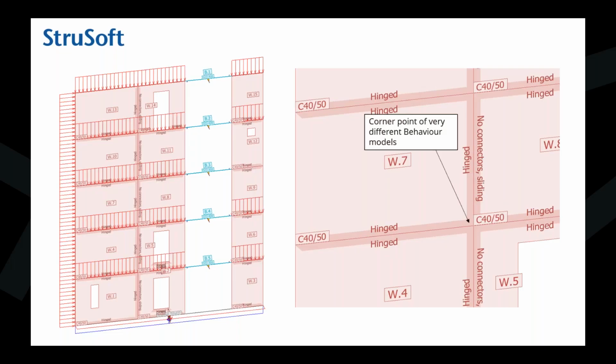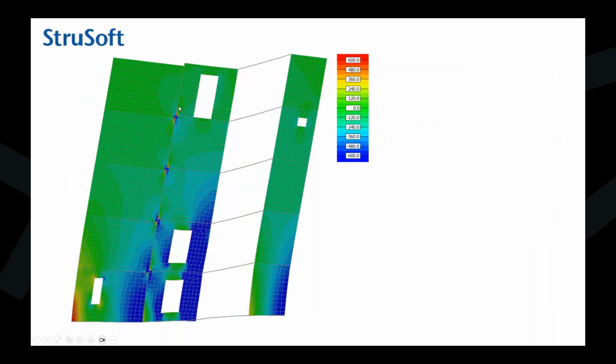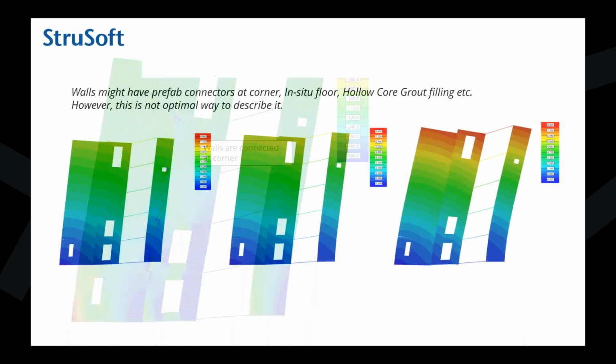And this is the point of contradiction. We have a lot of stiffness in the vertical direction in the horizontal connection, but the vertical connection can move. And if you calculate the finite element model, this will happen. If you look at those corners, there's something wonky going on. There are a few clients who use it to their benefit, but I always advise not to do that, because